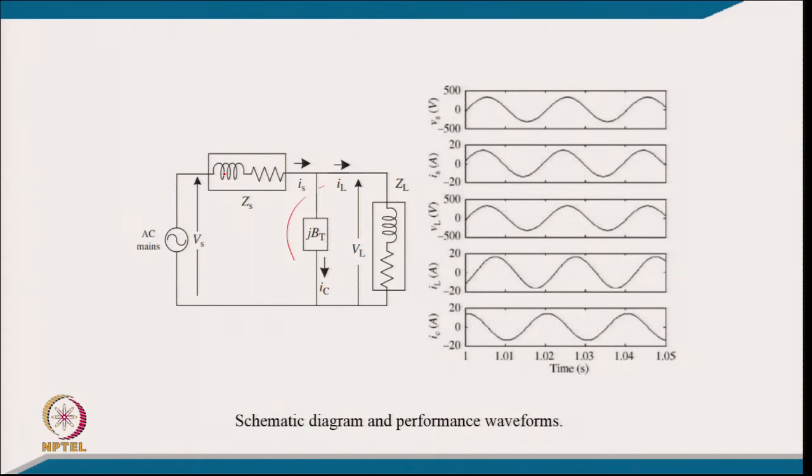Well, of course, you can see here, we put the values and made this waveform for the actual data, and you can see the source current is slightly leading the voltage. So, even for zero voltage regulation, meaning whatever is the source voltage should be equal to the load voltage, it will always come with a little leading power factor, because your source impedance is of inductive nature, and that is the reason you can see all the parameters here.